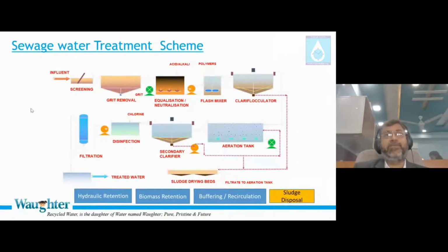I presented to them a different picture. If you really go across any river in India, you will find in the majority of places even a bar screen is not there. Even a dog which dies in a nala goes all the way to the holy Ganges. So do not spend all your money on a hi-fi treatment of sewage, looking for big space, primary aeration and all that. You go in phases. In the first place, at least make sure that the nala is not kacha, it's pakka, so that you can have authentic data of how much flow is flowing in that nala during normal weather, normal rainy weather, or during incessant rain. Right now you do not have any data. You have a hypothetical model.